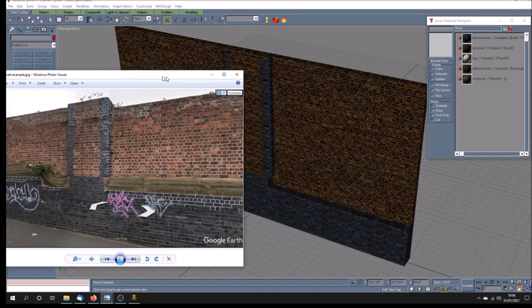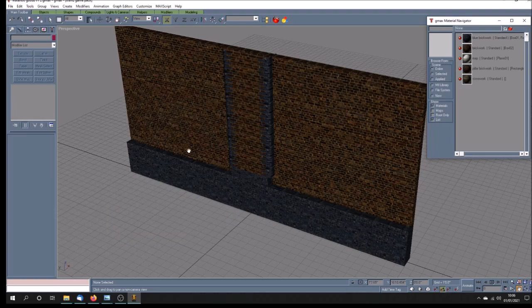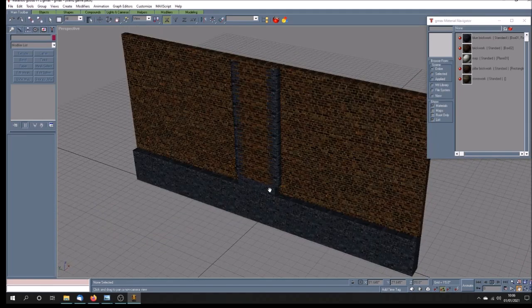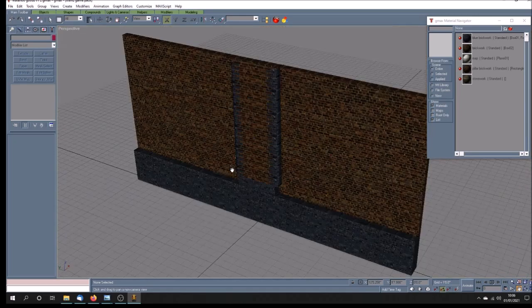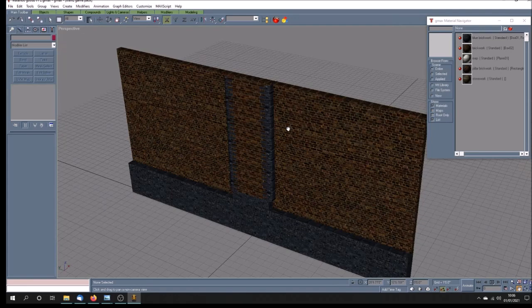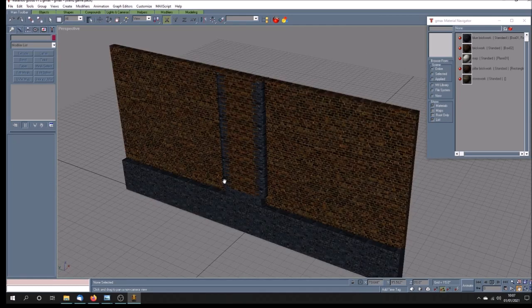What I may do actually is I may reduce the quality of these two, because that will then reduce the hit on the graphics cards. So I'd much rather have these looking like these here than to try and work this up into a much more sharp, detailed texture, because it just makes for a massive model, which isn't necessary. Also, I've got such repetition here on this texture. I need to address that. I need to lose that by making these much more uniform.